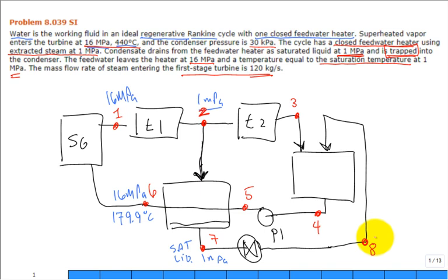The next thing we do is we talk about fractions of flow. We know that a certain percent of what went into the first turbine is diverted to feed the closed feed water heater. Well, let's put that as Y. Y in parentheses is a mass fraction, the notation used in the textbook, about what's diverted. So what continues is 1 minus Y. What continues through 3 down to feed this condenser right here is 1 minus Y. Right? But it's 100%, a 1 in parentheses, that's notation used in our textbook, for what feeds the first turbine.